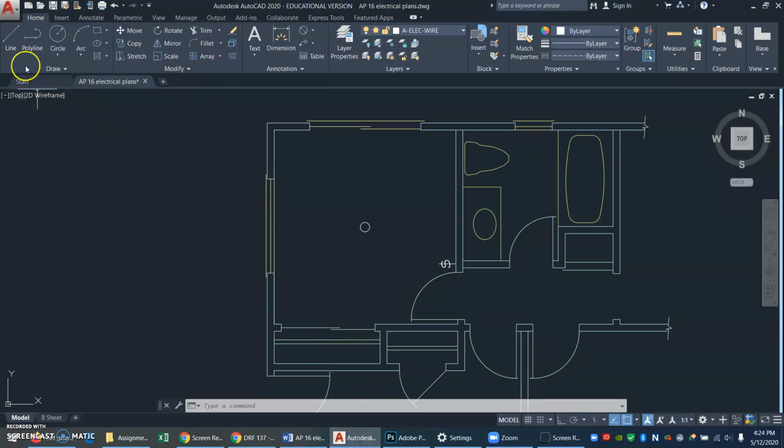So for that, you might want to consider going up here to the Draw ribbon and getting a thing called Spline. And notice there are two flavors of spline. You want the first one, and you can see the picture shows there are grips, there are points right on that squiggly line. If you do the second one, the grips will be out in space and it's annoying.